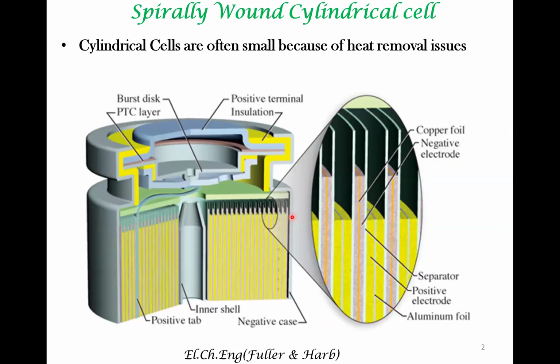Why is that? Because we assume that the temperature variation is only along the radius. There is no variation in the axial direction as well as the theta direction. The only variation is along the radius. So it eventually becomes a 1D problem that you must have solved in your heat transfer classes, especially when you are thinking about heat transfer in fins and so on.